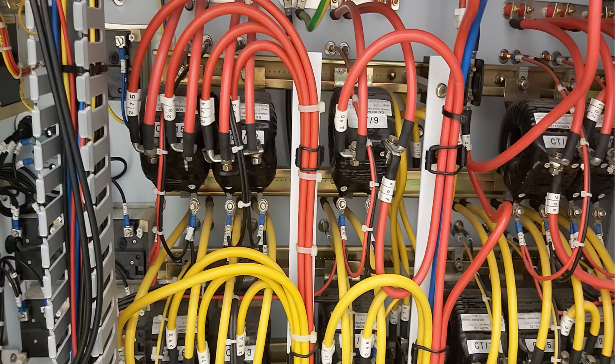Let's have a look first at the CT from the back side of the simulator. This is how the CTs look, and they are numbered like CT9, CT8 according to their connection to the relays. Those are the primary, and you can see those wires are also numbered, so it is easy to follow the connection. And those small wires there are the secondary. You can see S1, S2 written there for secondary, and B1, B2 for the primary. So the secondary are connected directly to the relays.